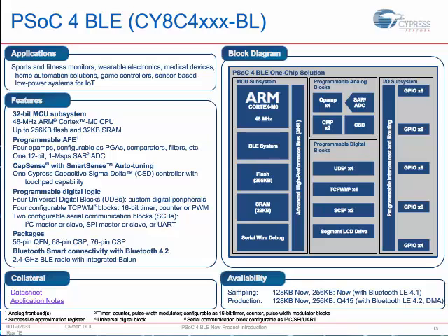The BLE subsystem is obviously fully integrated into this chip. The Bluetooth controller, the Bluetooth balun, all you need to do is hook it up to an antenna, and you're ready to go to communicate wirelessly. The chip includes 256 KB of flash and 32 KB of SRAM. It is also available in a 128/16 KB version if you're interested in that.